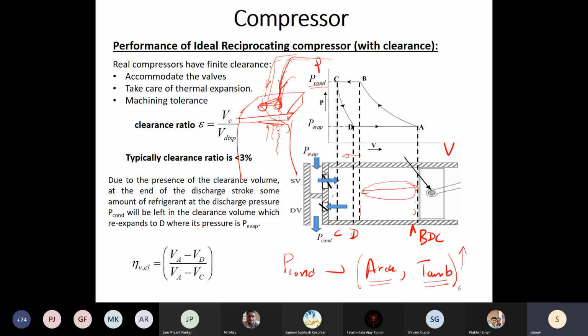Disregarding any leaks, if you have continuous operation of a compressor, this is one of the issues that most compressors will have. That's why we have open compressors where we can change the valves. This is a common failure. But if you disregard the failure of the valve where it doesn't close properly, in the ideal case, when the pressure inside the cylinder goes higher, this flap will close just by how the flaps are placed. Does that answer your question? Yes, sir.